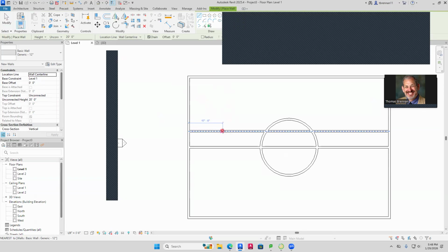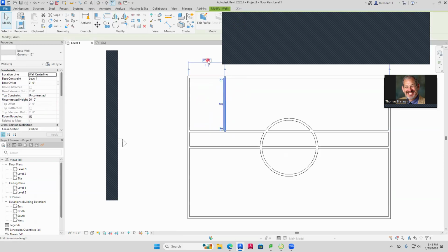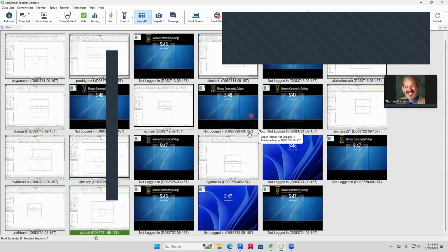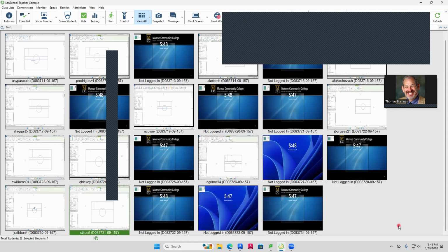And if it's not 16 feet, let's say I make a mistake. I click there and go up, and it's like, oh no, everything's ruined. Well, it's not. You press your escape key, you click on here, and you just type in the right dimension. Instead of being 18, I type in 16. So it's very forgiving. It really will let you get away with murder. It'll let you do all this stuff. So you got that one, and that is going to be 16 feet. Just use your temporary dimensions to get it in place, and you're good to go. Awesome. You guys are doing great.